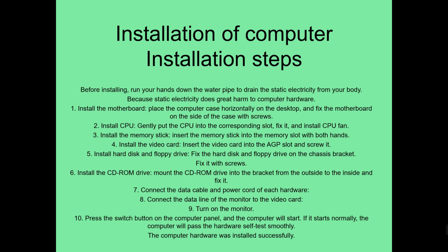Fix it with screws. 6. Install the CD-ROM drive. Mount the CD-ROM drive into the bracket from the outside to the inside and fix it. 7. Connect the data cable and power cord of each hardware. 8.